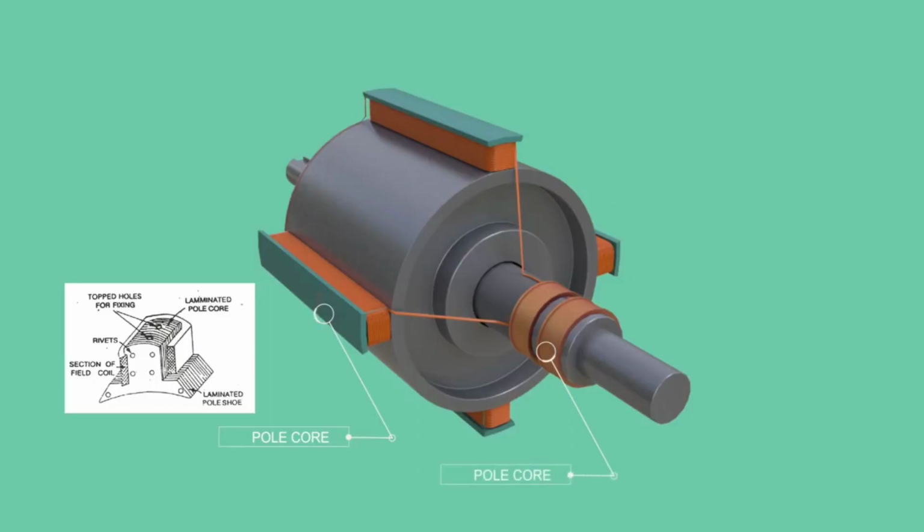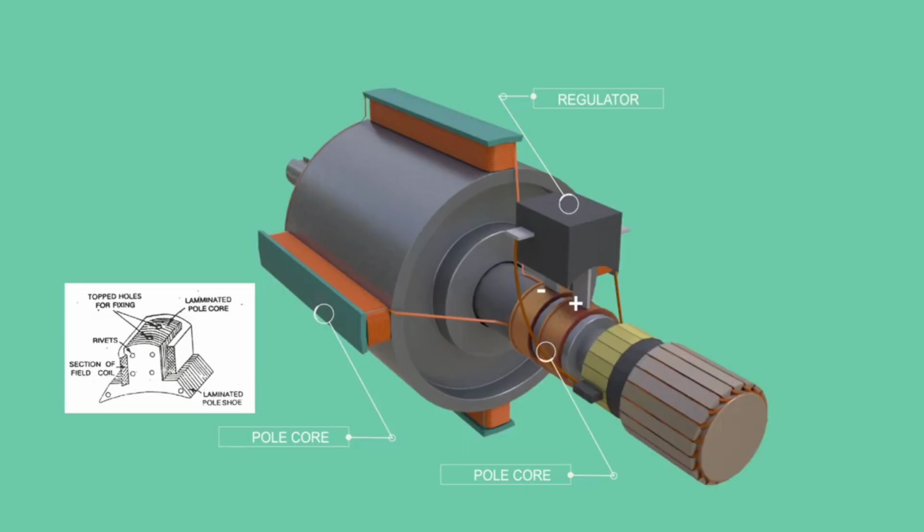DC current is supplied to rotor with a pair of slip rings. This is the reason why a rotating magnetic field approach is used in alternator. If rotating coil method were used, slip rings have to fit it along with the armature coils in order to collect electricity. But transferring such high voltage electricity with slip ring is rather impractical. It is quite possible to transfer low voltage DC excite current with slip rings.